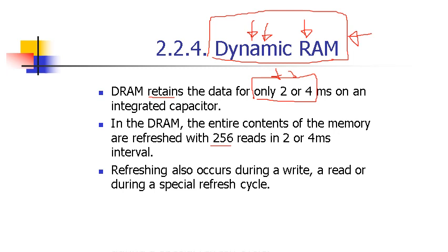Dynamic RAM stores the ones and zeros inside a capacitor. All right, and capacitors are usually leaky electrical elements, so they lose the charge through the connections. So you have to refresh the data when using dynamic RAM, while the static RAM uses transistors to read and write data.